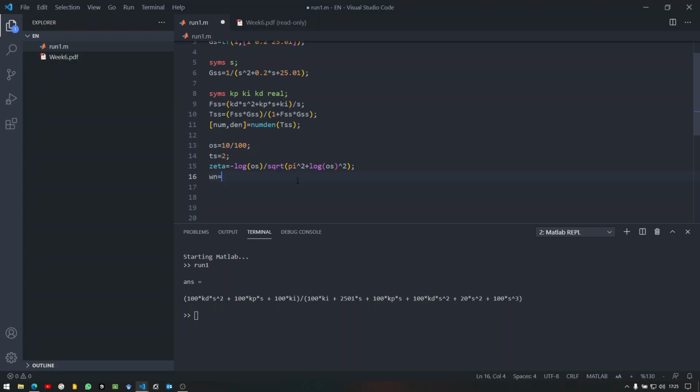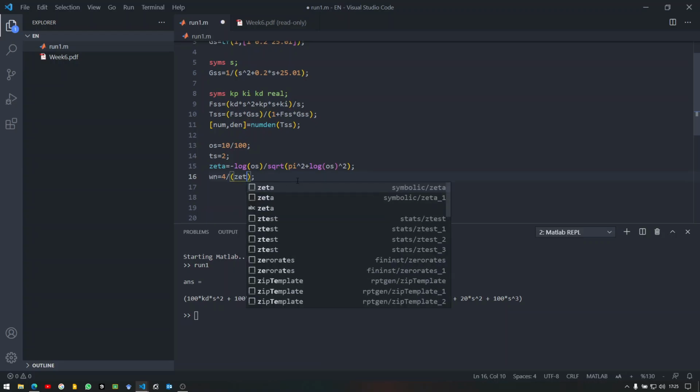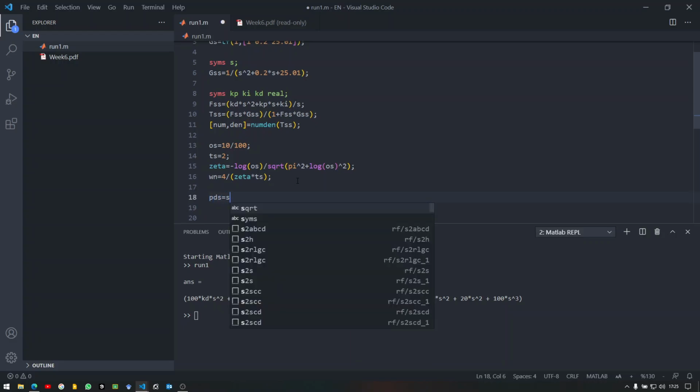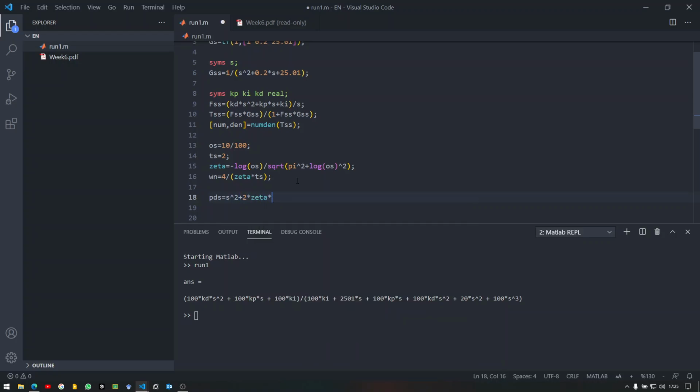And I hope, most of the time that is the case, that the other poles or zeros will be far left on the complex plane, so that I have a dominance there. So therefore I will need the settling time and overshoot parameters to provide me the corresponding zeta and omega n values, and based on that I can define my desired characteristic polynomial, that looks like a second order polynomial.